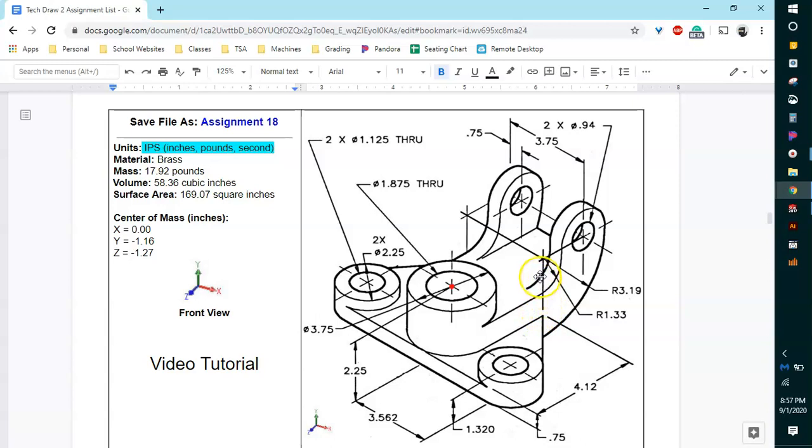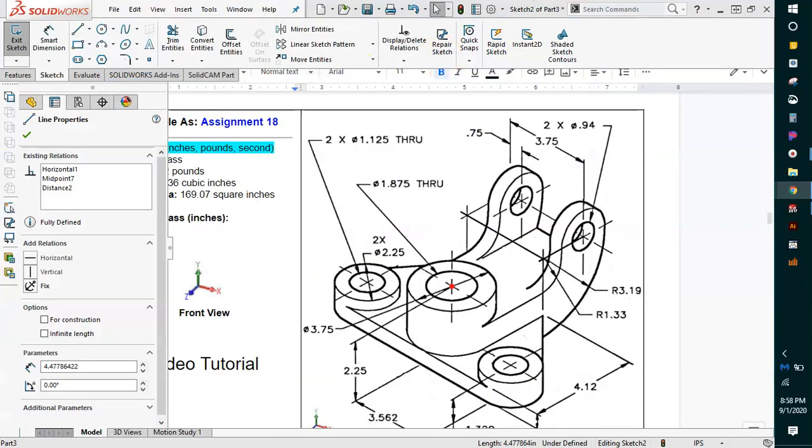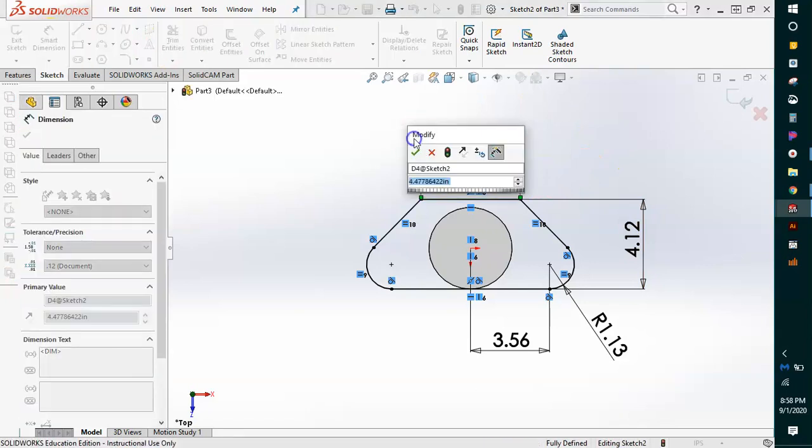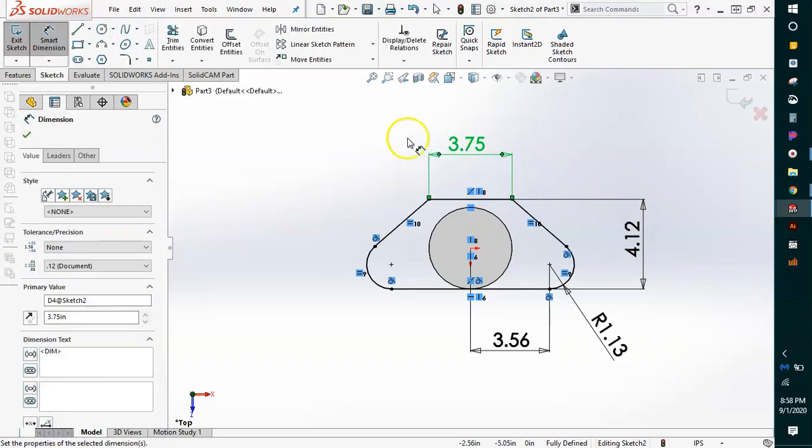And if I follow, you can kind of see my corner here. If I follow straight up, there'll be an extension line, and it looks like this is kind of like a crosshair where a whole bunch of intersections are. I follow that over, you can see that again, and it goes down. So what that's basically saying is from here to here is the same measurement as from there to the outside of here, which is 3.75. So you kind of have to follow these extension lines and read some measurements elsewhere. I know it is like a maze every once in a while to find the measurements, but you do need to follow those paths and try to learn how to read a drawing the best you can. So this says it is 3.75.